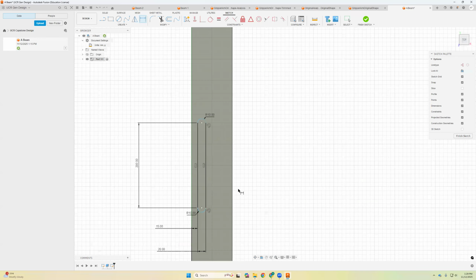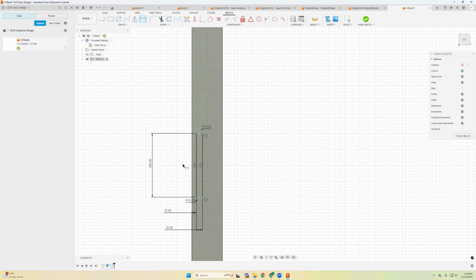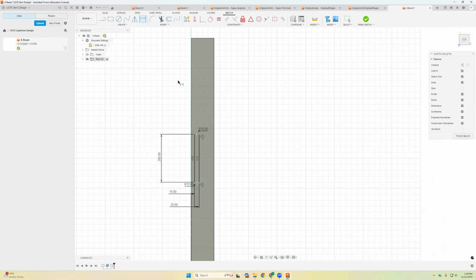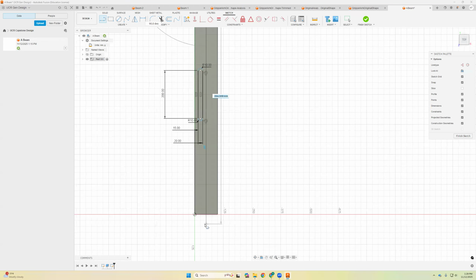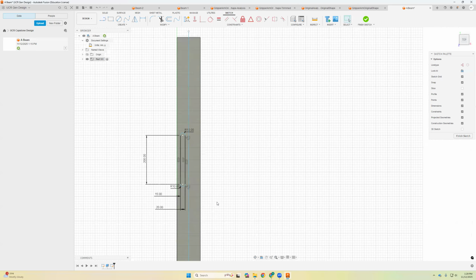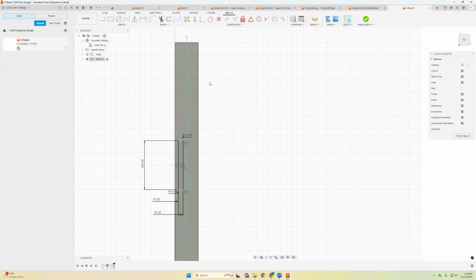All right. Now let's say this slot, we wish to mirror it. So I need to draw a line right in the middle. So that's the line. Always you can press Enter to get out of a command that you're doing, or Escape to finish that one.